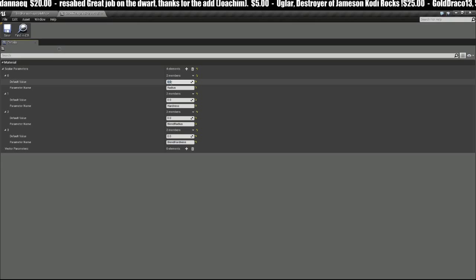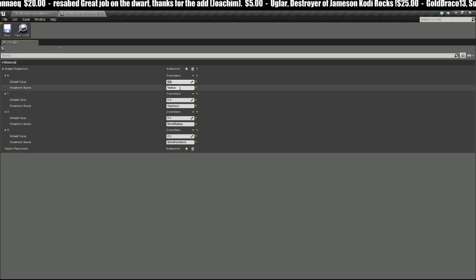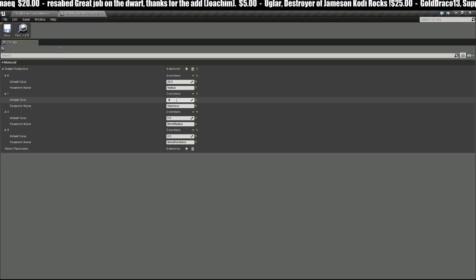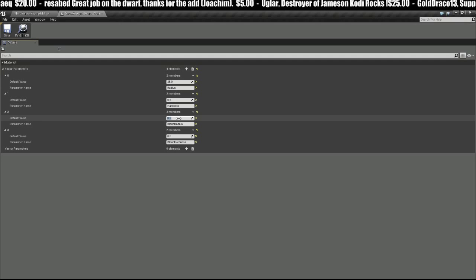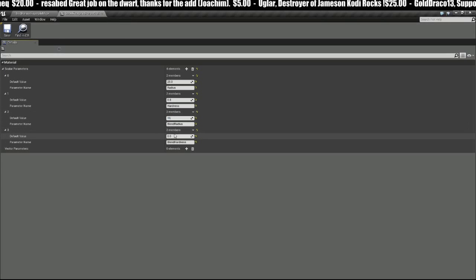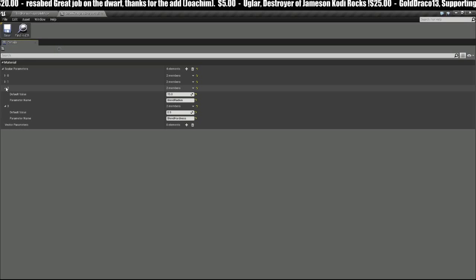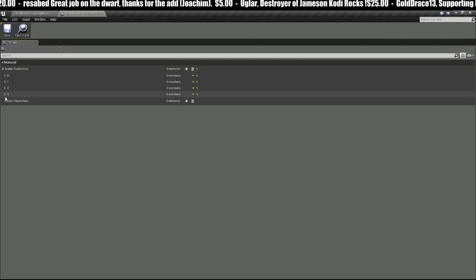And for the different sizes, this is what I have set. So 25 for the radius, 0.8 for the hardness, 15 for the blend radius, and 0.9 on that one. All right, so save that. We can minimize these, and I'll show you where we hook those up in a little bit.